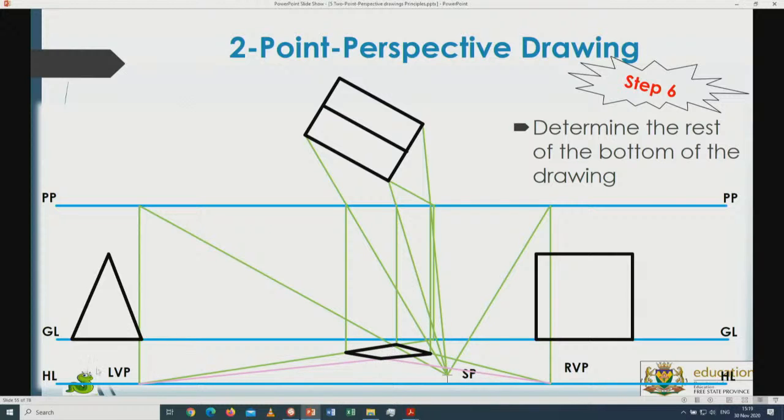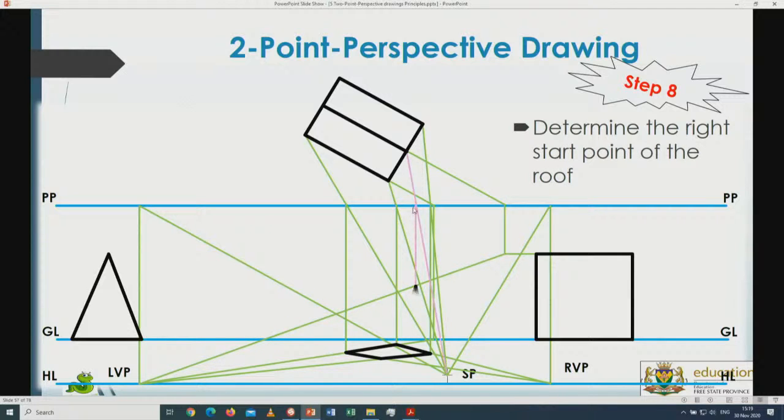I look underneath it. It's lower than the ground level, so I look at it from underneath the ground itself. Right, then this part extended. It's not standing on the picture plane, so it has to be extended, go downwards. That's the height. This will disappear to the left vanishing point, somewhere on that line. From there, it goes to the standpoint, intersect with the picture plane.